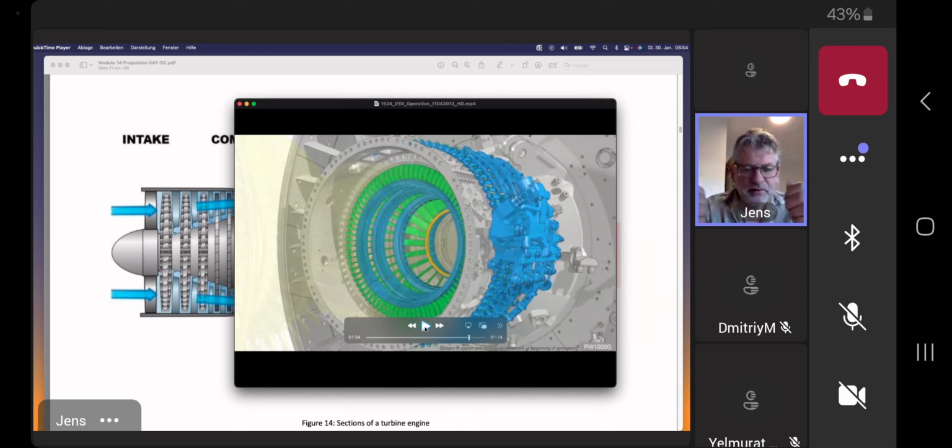And the other is the speed of the air through the compressor. Those two speeds make the angle of attack. In order to have the right angle of attack and to avoid stall, the angle needs to be adjusted, otherwise every engine would stall. That's why we find those variable guide vanes, especially in the high pressure system with high RPMs.